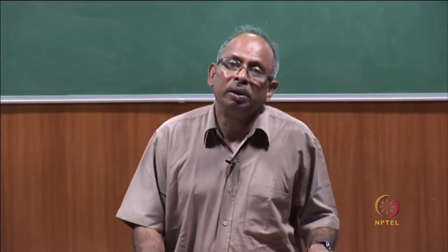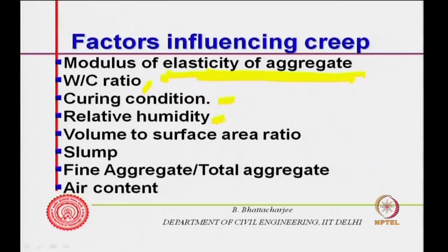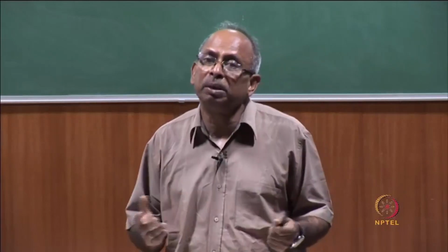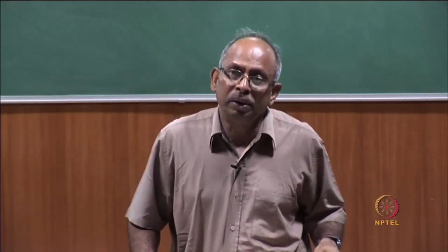So, therefore, curing condition becomes important. Relative humidity, the environmental condition we just mentioned before, and volume to surface area ratio are important, because depending upon the volume to surface area ratio, the evaporation rate, the movement of water outside the specimen or outside the element, would be governed by it.